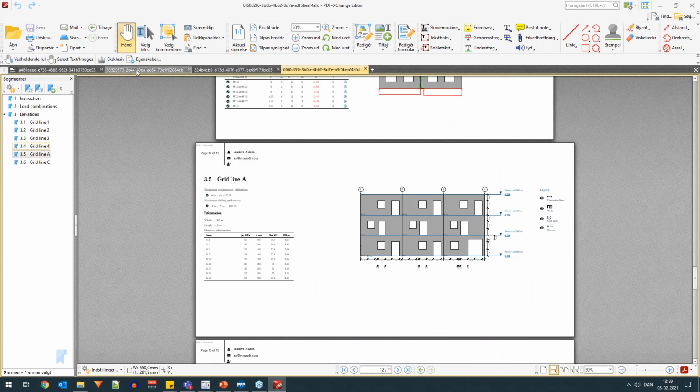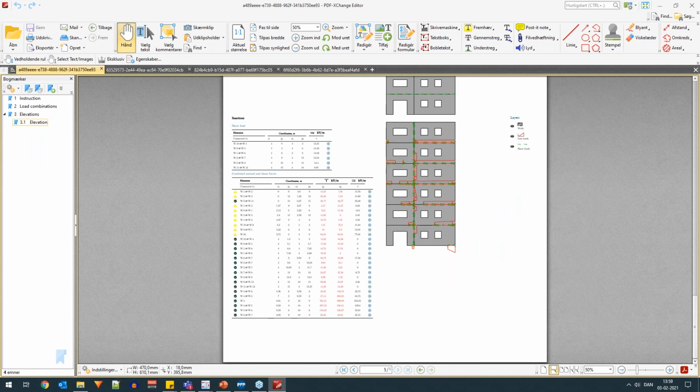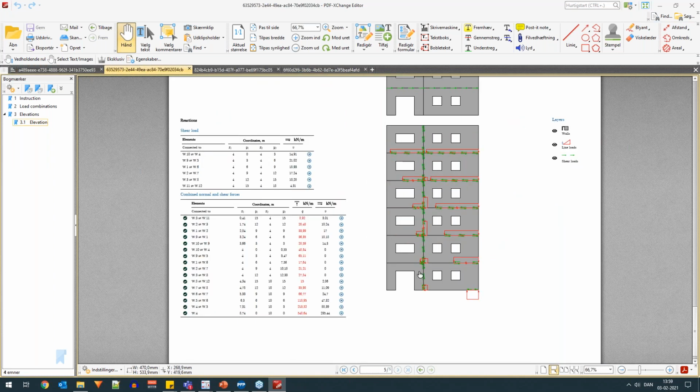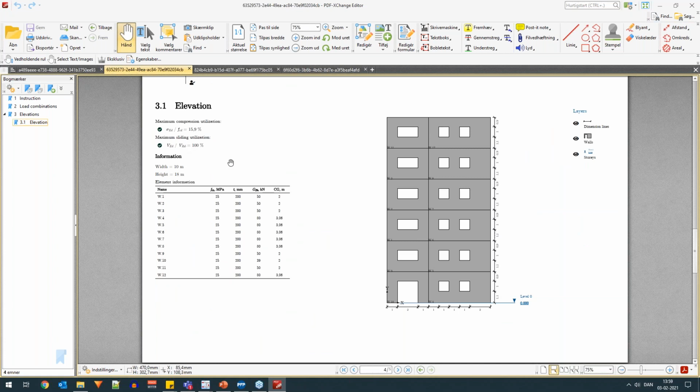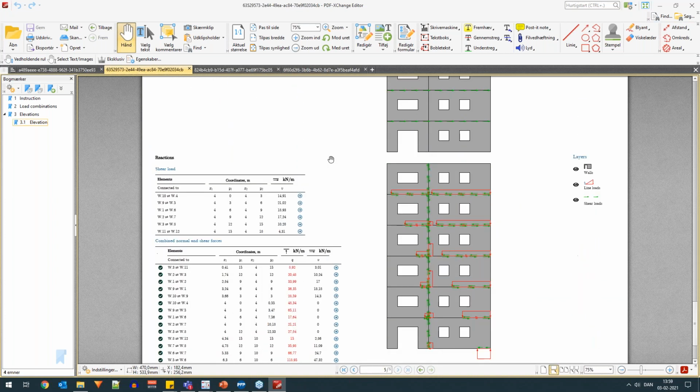Any sliding issues, as you saw on the first page here, we did run the plastic optimization as well on the exact same wall. It doesn't optimize to find the lowest value in sliding. It tries to not exceed 100%. So if any area is more than 100% utilized in sliding, it moves just enough so that the utilization is exactly 100%. Still, it is only according to the friction capacity.